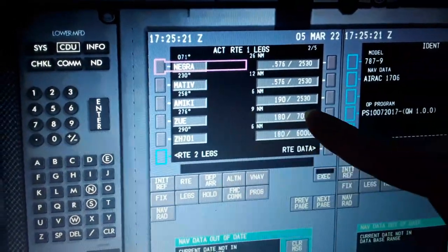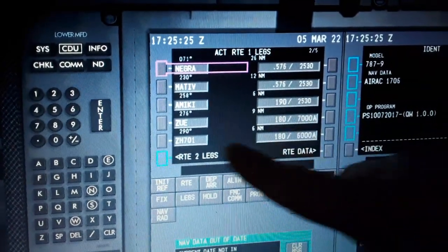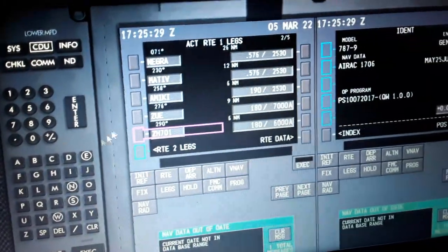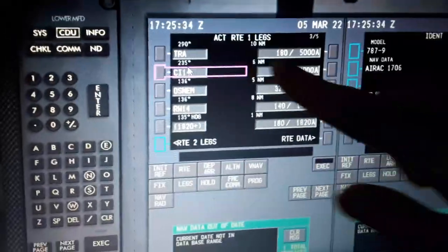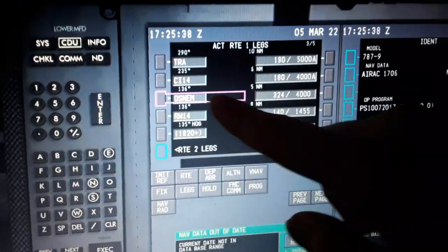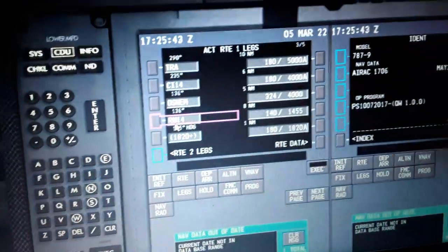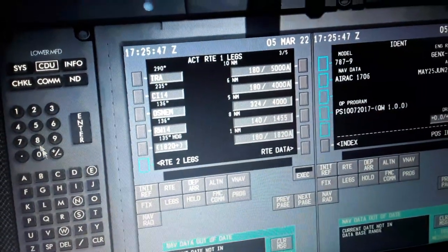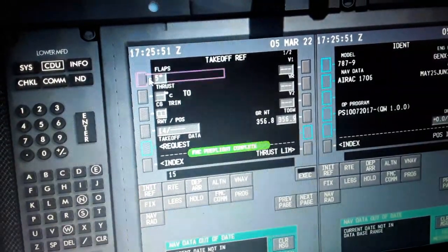We descend for approach and landing with the ZUI, heading 076 degrees, 180 knots, 7,000 alpha, Zurich 701, 6 nautical miles, 180 knots, 6,000 alpha, TRA, 10 nautical miles, CI 14, 6 nautical miles, Oznem. We make a left turn for alignment with the runway over here at Oznem, and also use the ILS localizer for approach to runway 14 and landing. 8 nautical miles, 1,440 feet.